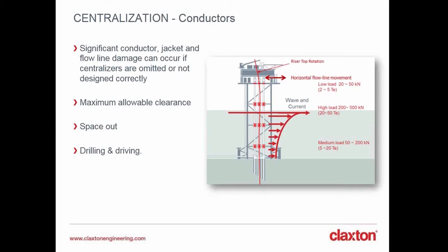It is important that the assumptions in the analysis consider the minimum required clearance just for running the conductor. So there's a minimum clearance that we need just to be able to run the conductor through the guides, and that RISE analysis should consider that and should make assumptions that are achievable in real life.